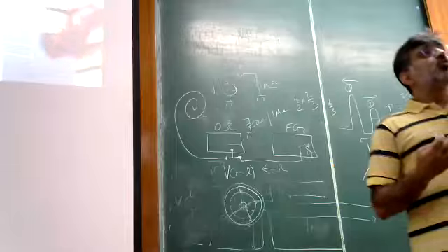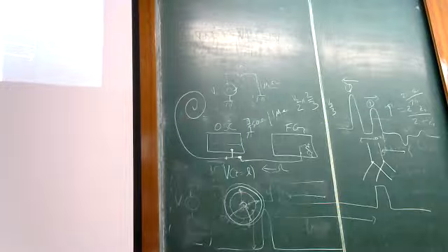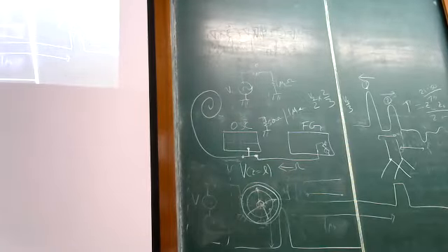So this is called overmoding in a coaxial line, and that basically gives you the practical upper limit of where you can use it. So for this type of coaxial cable, the one which I circulated to you and the one which is here, these guys have an outside diameter of 0.085 inches or 85 mil. MIL is a milli-inch. That's the terminology often used in machining. And that gives you a cutoff frequency of usually around 40 to 60 gigahertz. So these kinds of cables can be used to fairly high frequencies.